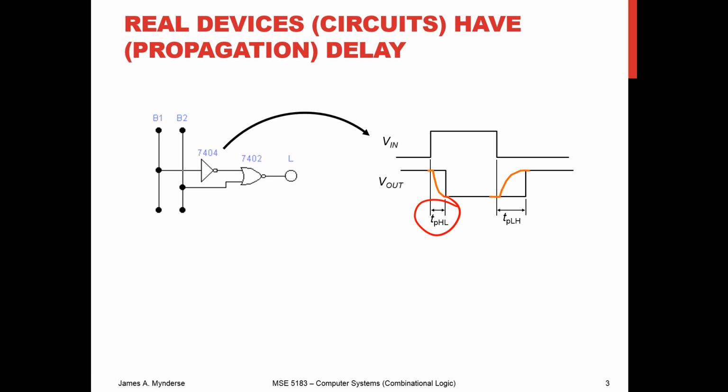With the input going from low to high, in our lab example, we talked about the delay time and the rise time, and we lumped that together as the turn on time. And then from input going from high to low, we called that the storage and the fall time on the back end there, and that was the turn off time.